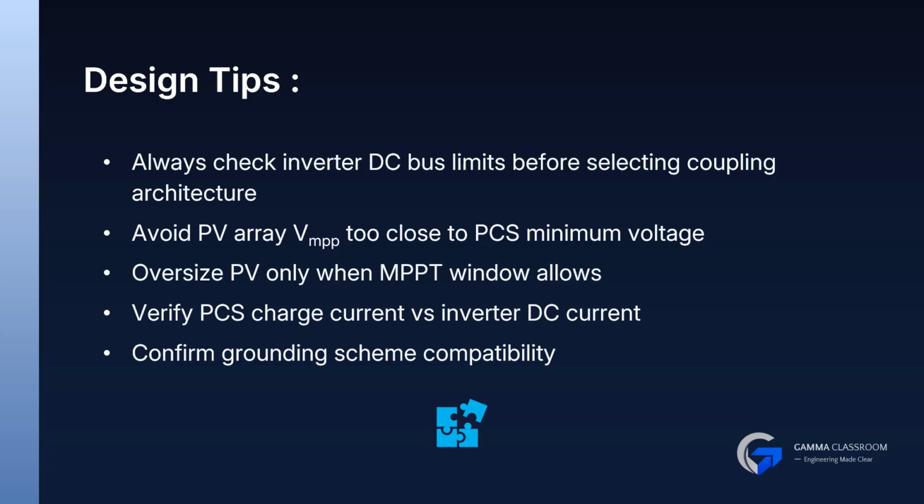Confirm PCS charge current does not exceed inverter DC current limits. Ensure grounding schemes are compatible across PV, PCS, and transformer. And always validate protection settings against utility requirements.